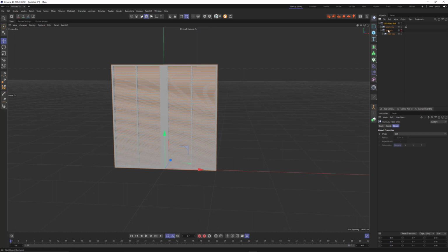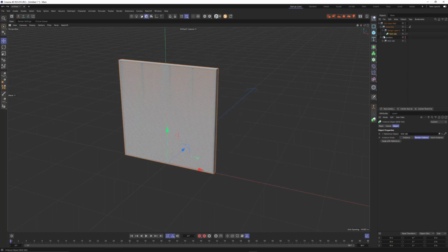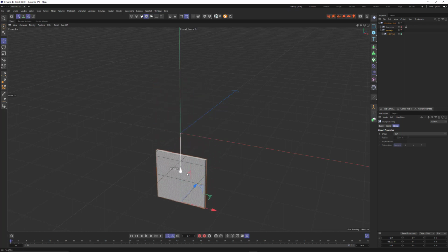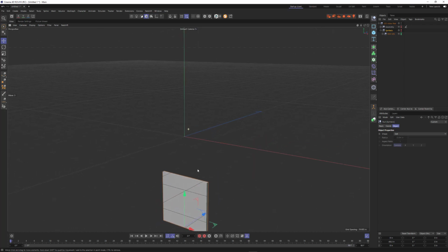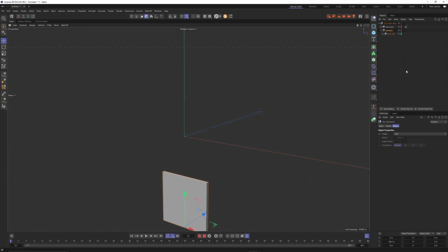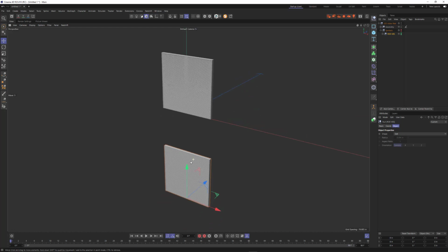Now, so here's what's happening. What we're seeing here on this design layer, this is an instance, right? So this is the instance here. And what we've got is a folder called symbol hidden, and the raw geometry is right here. Now, weirdly, it's in exactly the same spot, so that's confusing. I'm just going to take this whole folder here and just go zoop, and just sink it way down into the floor underneath our stage so we don't have to see it. Let's turn off the work plane filter. Hate that thing. And so now here, if we turn this on, so here's our instance, and here's the actual kind of hard geometry. So that's cool.